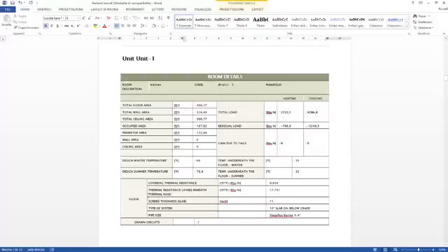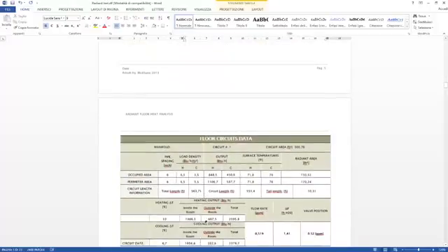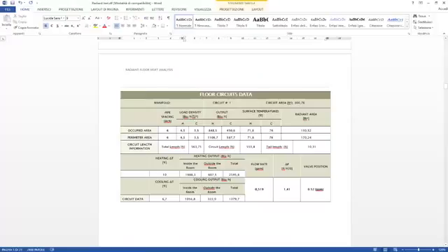Our bottom section here is designated to our floor, which are covering thermoresistance. Our thermoresistance layers beneath the thermal mass, our screed thickness or slab, our type of system, and our pipe size. Finally, we have how many circuits are drawn in this room, which is 1. Further, we come to our next page.